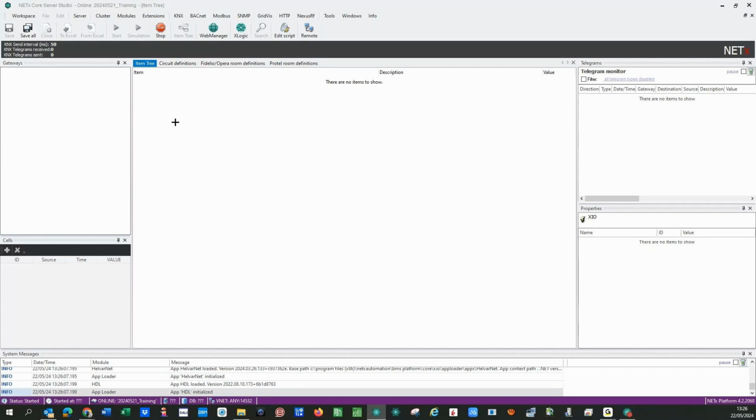But you have to consider that, because if you only think of your lights and shutters and HVAC data points from KNX and your BACnet or your Modbus, and you don't consider these 1,000 data points needed for the 200-room hotel, you will need to upgrade your license afterwards. So it's important to understand this.